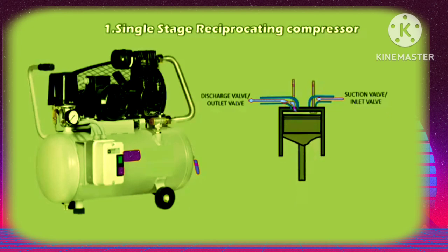When the piston moves upwards, it compresses the air in the cylinder, and the inlet valve closes when the pressure reaches atmospheric pressure. Further compression follows as the piston moves towards the top of its stroke, until the pressure in the cylinder exceeds that in the air storage. This is the compression stroke of a compressor. At the end of the stroke, the discharge valve opens and air is delivered to the air storage tank.